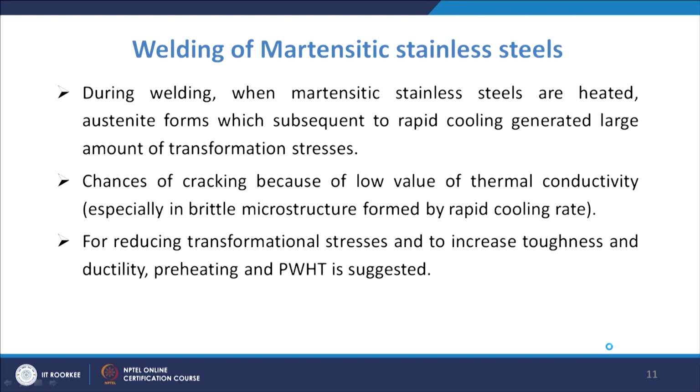Also it has a very low value of thermal conductivity. So, you will have the chance of cracking, especially when you have the brittle microstructure formed because of the rapid cooling rate. This is normally possible in these kinds of steels.